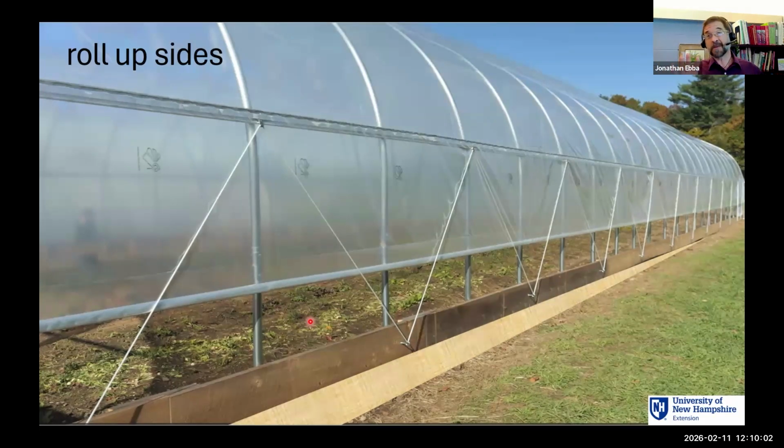And if we're putting up something to block thrips or spotted wing Drosophila, we might be removing 80% of the airflow, right? So as we're figuring out how much open area we need, we need to know how much we're impeding that with any screens that we're using. And so the amount of open space here, we can express as a percentage of the floor space.